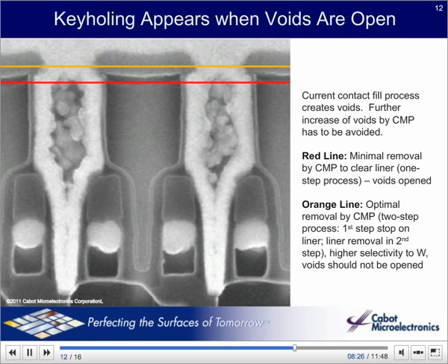Here you can see how CMP can create or reveal a flaw in the microstructure. CMP is often blamed for creating defects that are actually intrinsic to the metallurgy and the deposition process. In this case, CVD, chemical vapor deposition, was used to deposit tungsten. CVD starts by depositing metals on the walls and working its way in. When the grains grow together in the middle, there are often voids. Other examples of CMP revealing problems include imperfect alloys such as copper in aluminum or silicon, voids from electroplating, or inclusions from debris during the metallization. We'll hear more about defects later.